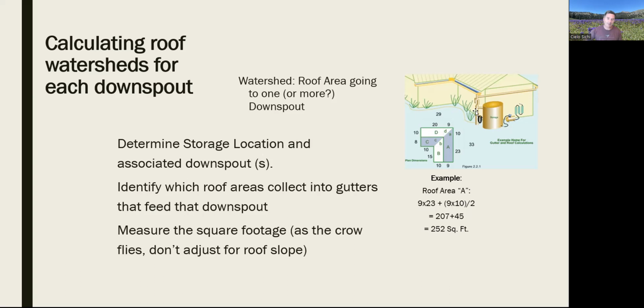Okay, so if that tank gets filled up, that tank gets filled up. You can use it during drier periods of the winter and then try to reuse it and then fill it up before the last rains. Okay, so you don't have to do as large as the amount of water as you can collect. Do as big as you feel comfortable with from a financial standpoint, as well as the standpoint of actually fitting that storage tank within that space.